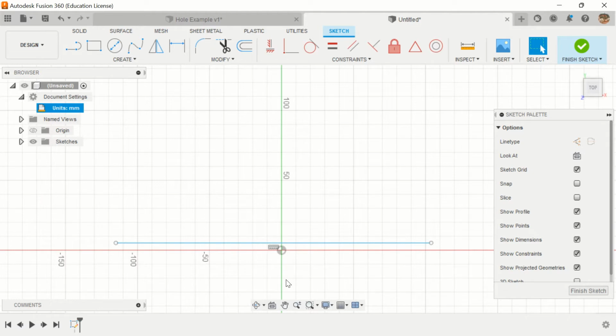All right, make line 2 coincident with line 1. So this is line 1 right here. Make sure when you highlight it that the whole thing highlights. I'm going to open up my line tool again. Coincident, so see how that box popped up? That means that Fusion is going to automatically apply a coincident constraint. It's very intuitive. It just means that lines 1 and 2 are going to share an endpoint. So most of us would do that.